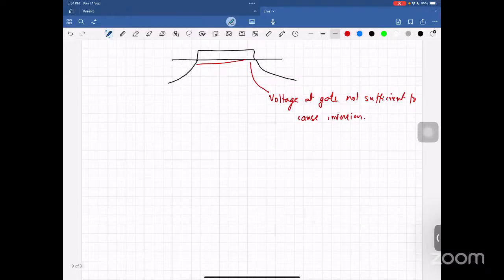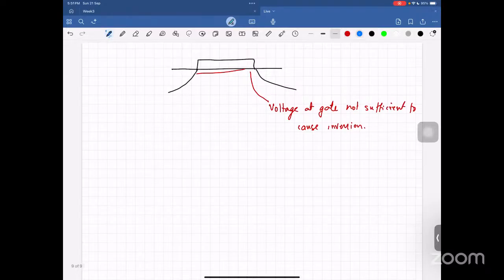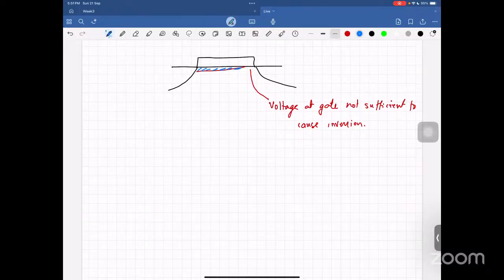Okay. So in effect, even though this is shown as a linear variation of inversion charge, it's not quite. There is some decrease in density, but essentially till some region you have some inversion charge, and then there is a region of space where there is no inversion charge. Is this making sense so far? So there should be a pinch off. Yes, sir. Now the question is, at what voltage will this pinch off occur?